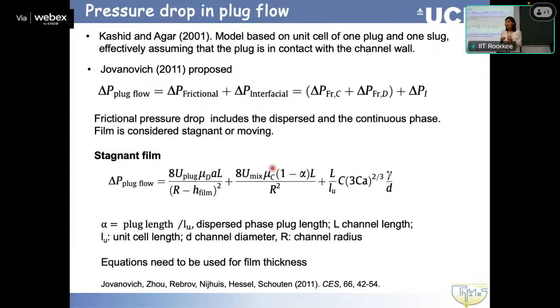So there are a lot of ways to try to calculate pressure drop in two-phase flows, starting from empirical, and some more semi-empirical or very simple, let's say, analytical ones. I don't have it here, but maybe I should have said it. In liquid-liquid flows, in most cases, we are dealing with water and some solvent whose properties are not that different. It's not like having a gas and a liquid. So these pressure drop correlations that assume average properties of the phases are very quick and they're not bad. If you want to do a quick calculation, just use what we call in two-phase flows the homogeneous model, where you average the properties and total flow rate, and you can find a decent pressure drop answer.